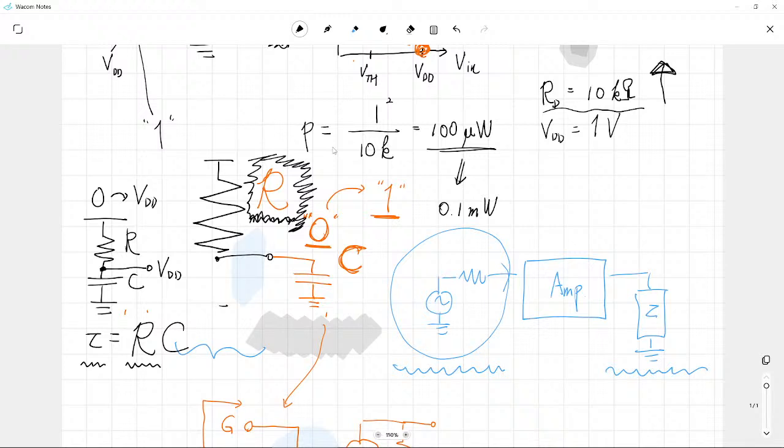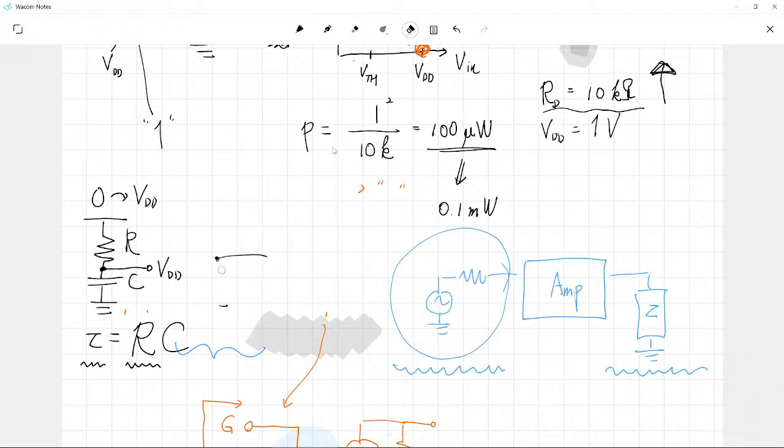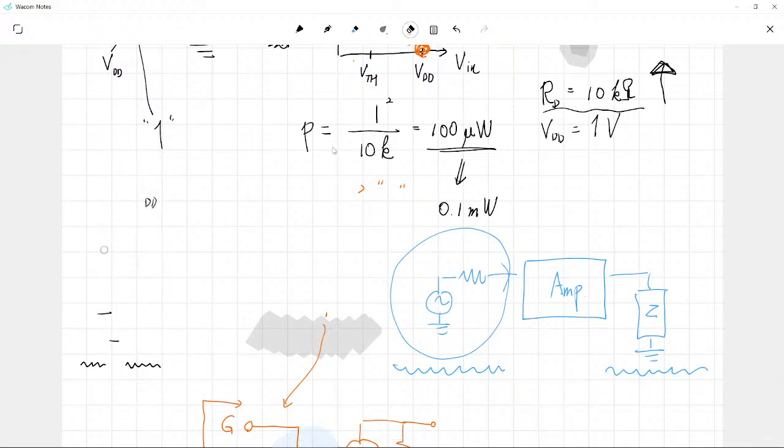If you just increase the resistor 10 times, then immediately you have a 10 times slower system. Can you live with this slow system? Maybe not. So in any way, it is not very convenient for us to work with this NMOS inverter, where the upper part is just made of a resistor. So now you understand why I made a long discussion about why the NMOS inverter is so bad.